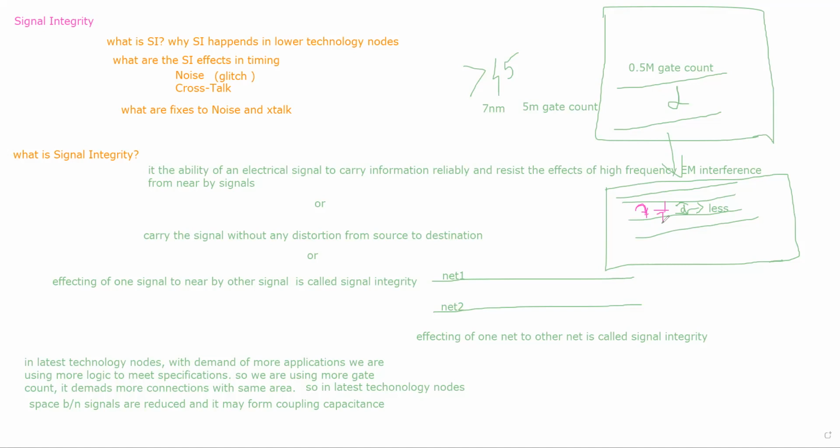During the implementation of CTS, what will the design engineer follow, right? So it's kind of caring. In your daily life, if you have one apple daily, it's good for your health, and you can avoid going to the hospital. The same here also. During the CTS, we'll take precautions to fix the crosstalk on clock nets, by using NDR rules, shielding and some other methods to avoid crosstalk on clock nets.